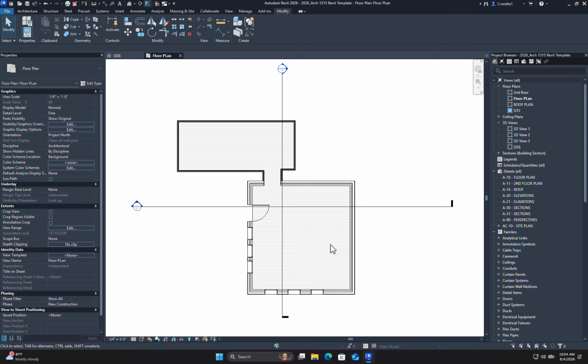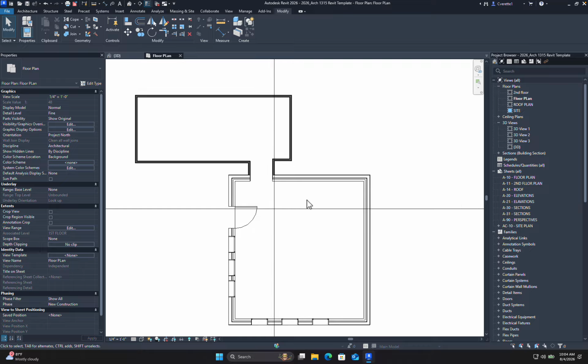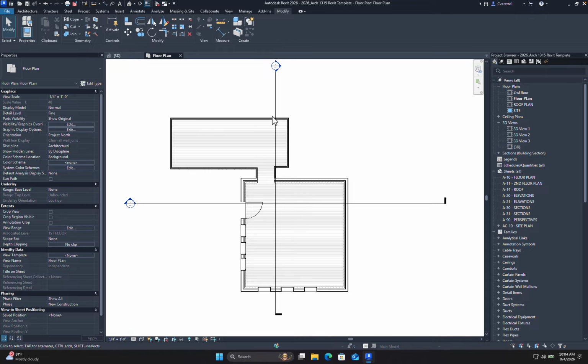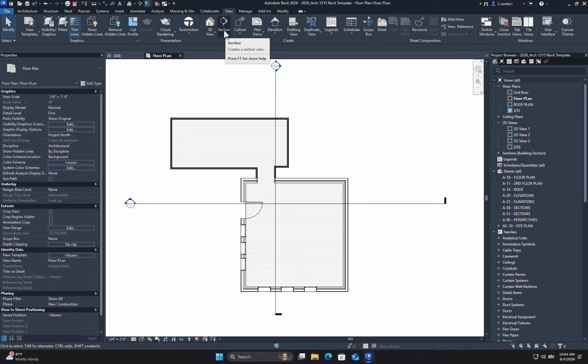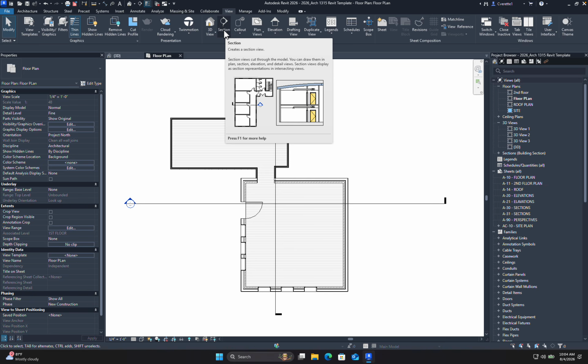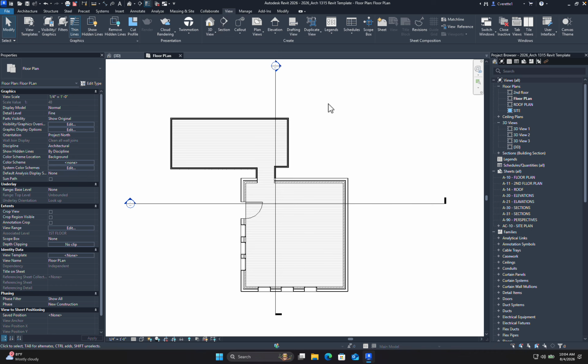In my case, one of the requirements is to make this a 2-story. So I do want to start talking about stairs, but I forgot. I was going and talking about elevations because I do want to set the standard of how high something should be. Keep in mind, this is not an intuitive program. It's almost like I've already designed it actually in AutoCAD, and now I'm making a construction document. So some of those things I've already decided, like a 12-foot floor plate in terms of, well, I want from my floor to ceiling to be 9 feet, and then the top floor to be 12 feet. I do have to make these decisions already, typically before I even get into Revit, because they're a little bit difficult to change once I've locked in some certain items.